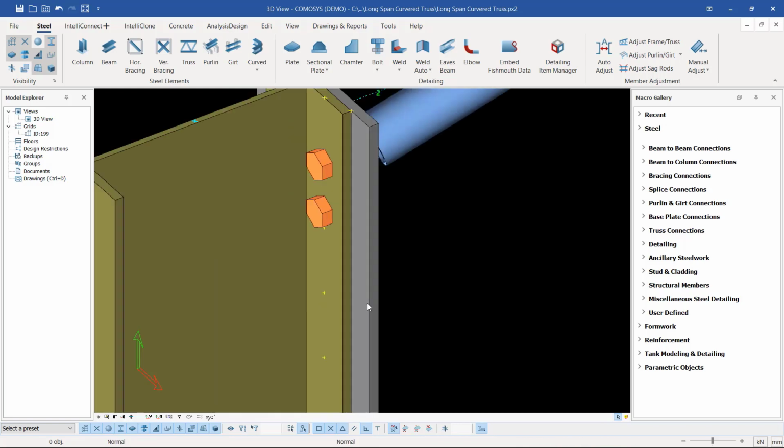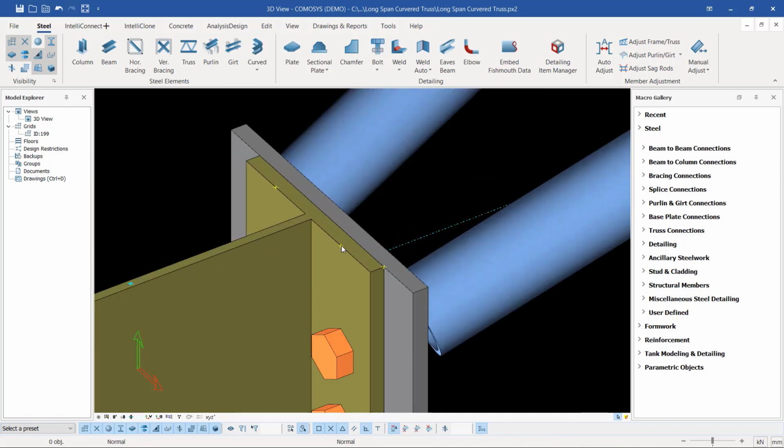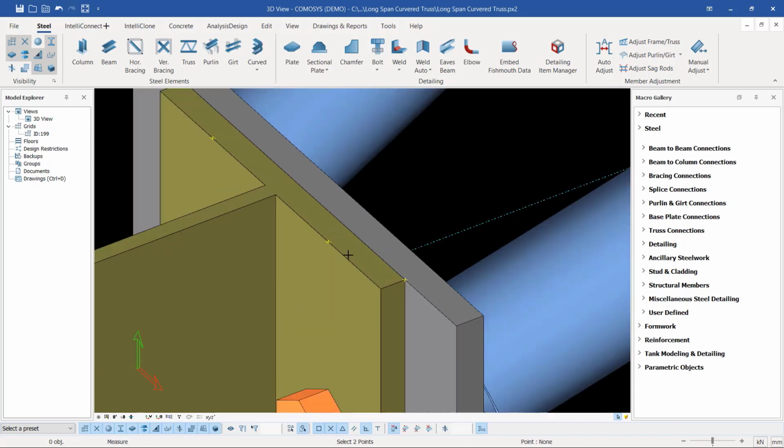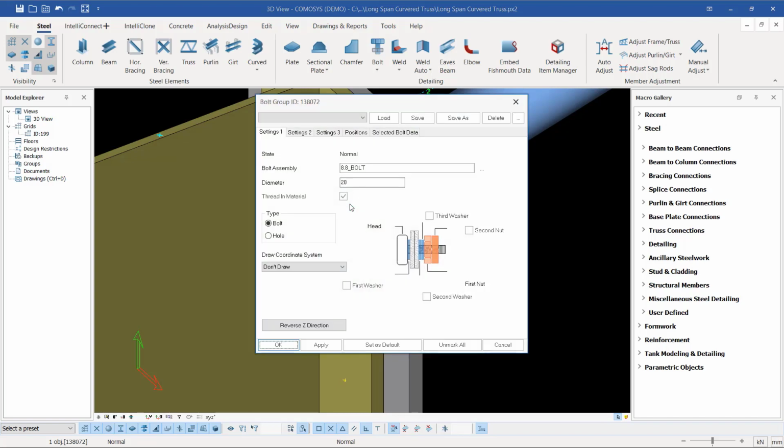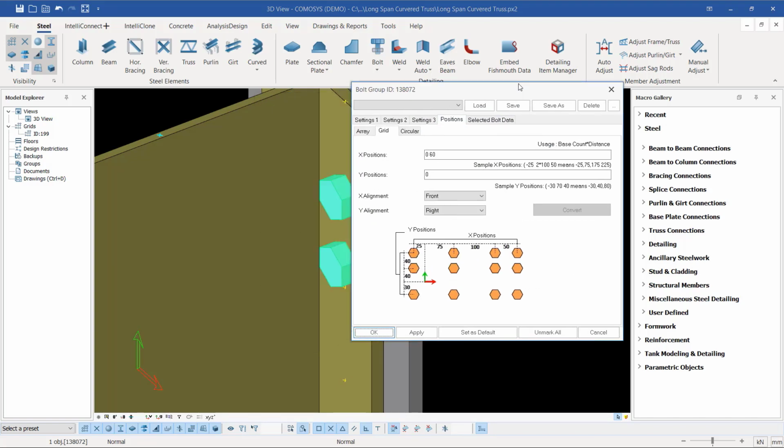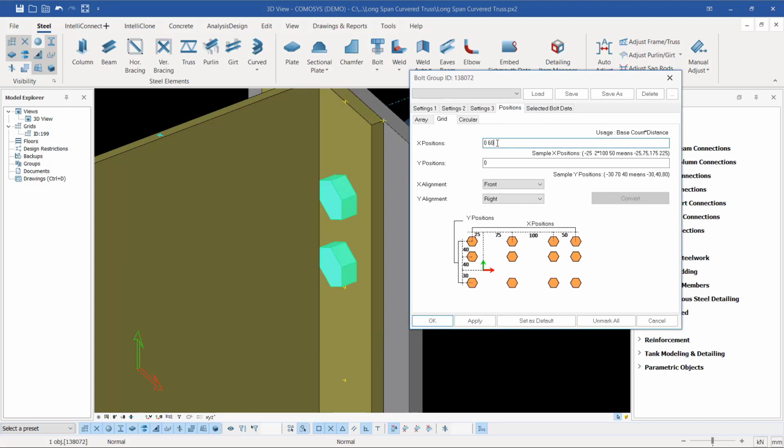And also let's confirm this from this center to that center. Let me right click and come to measure distance. I'll confirm this from here to here. That is 78.55. Correct. Now let me select the bolts once again and press letter M and enter on my keyboard, then come to positions here. I'll be able to feed in 83.125.